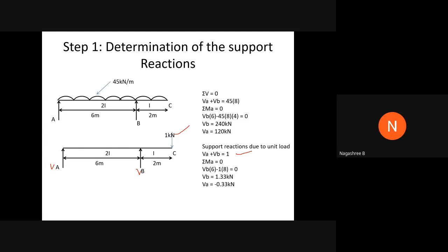So the next thing is the moment about A that I have considered. Previous to point A you have two points, that is VB and the load acting at point C. So it is VB into this distance, VB into 6, acting in the anti-clockwise direction. From the right side, anti-clockwise is considered to be a positive value. So VB into 6.